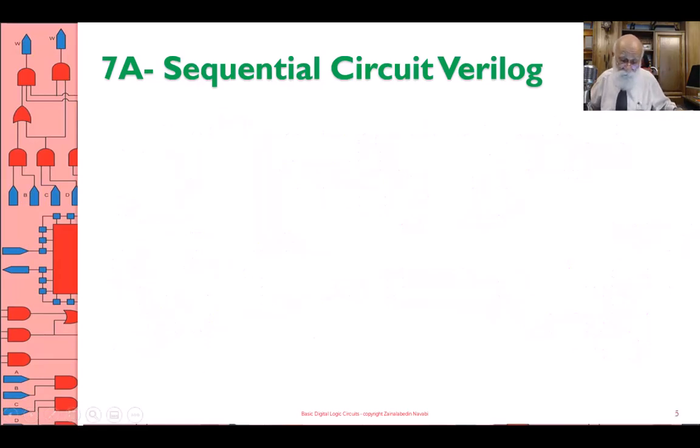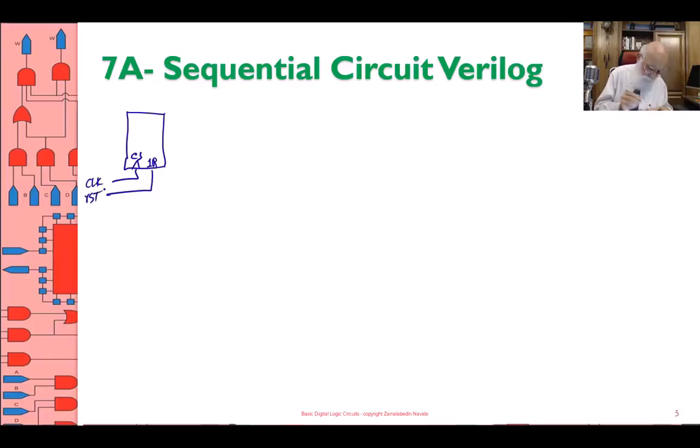I'm going to do a symbol for synchronous reset, C1, and then I have 1 R. That means it's synchronous. The 1 on the left-hand side, on the right-hand side of the clock, is used on the left-hand side of R. This is my clock. This is my reset. This is my Q. This is 1D. So the 1 that you see on the left-hand side of the R is also on the left-hand side of D. That means both of them are controlled by the clock.